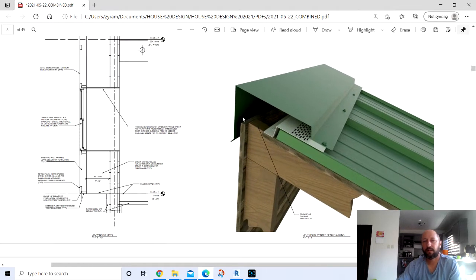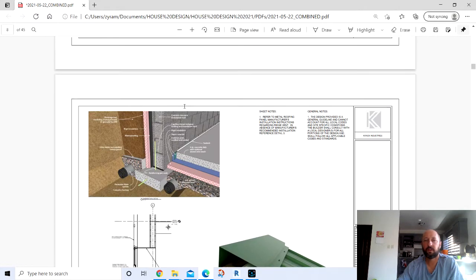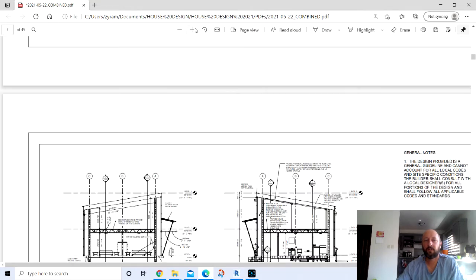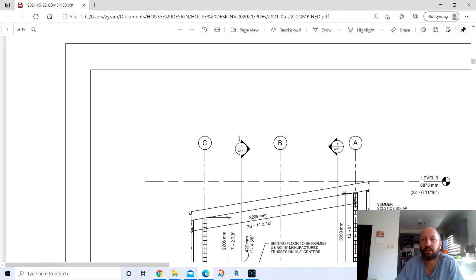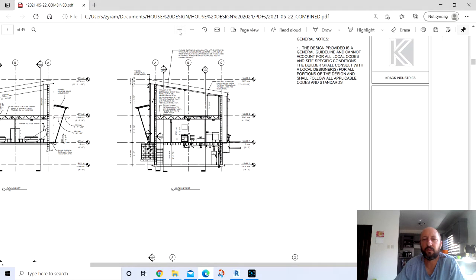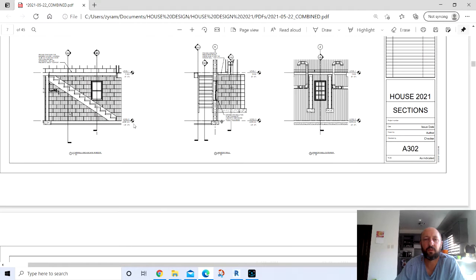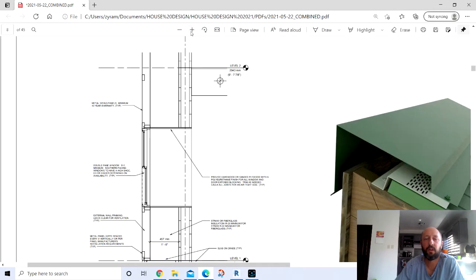So they call this roof type a shed roof that slopes one direction, because it's commonly used on sheds. The only disadvantage I really thought to having a roof shape like this is that they're not supposed to be the best for high wind areas, so you might want to check your requirements. And of course, we'll make sure and have strapping down from the concrete to the I-beams that are running through the roof, because in high winds, those roofs can be an issue. So if you've got really high winds, you might want to look at a different type of roof structure.